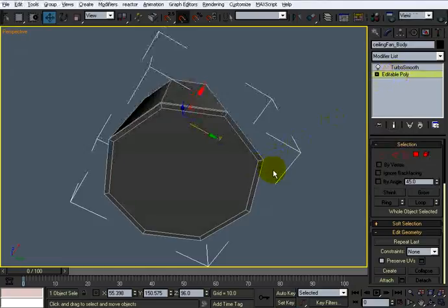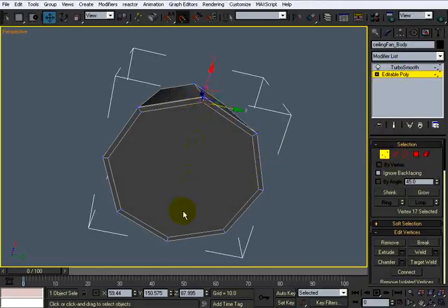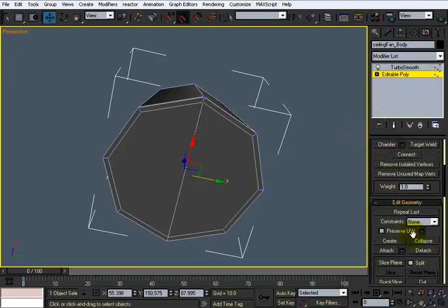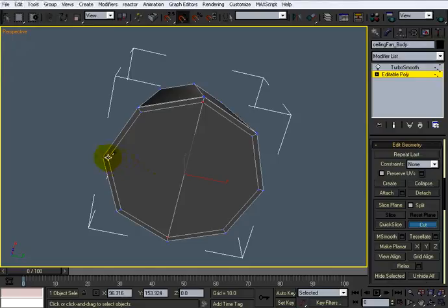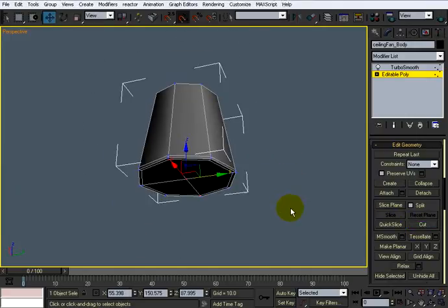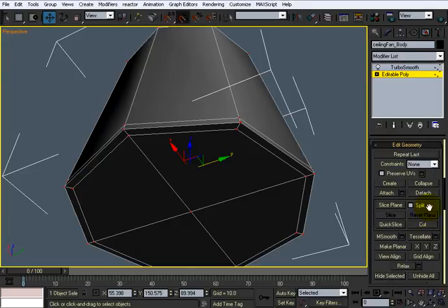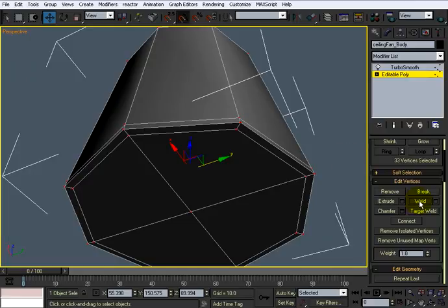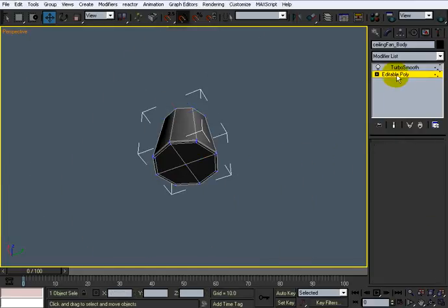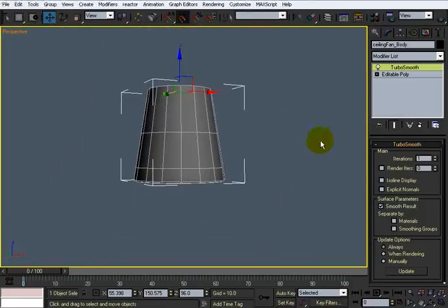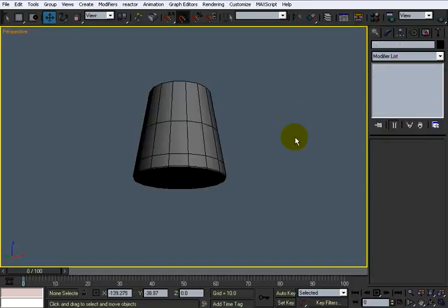Alright, to go back into here, what we can do if we want to is to just connect these so we can get all 4 sides. So I'm going to take it to there, and do like that. And now we have that. Hit Control A while I'm on my vertices, and I can just hit weld. I should be able to hit weld to see. Make sure everything's together. Alright. I'll hit Turbo Smooth, there should be no problem. And there isn't. And I'll do that sometimes to make sure that my connect is working correctly.